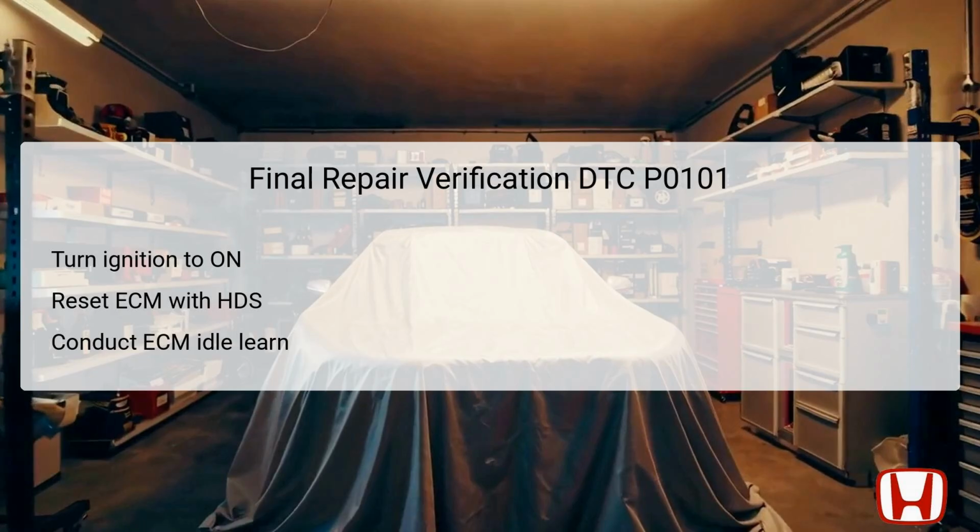Begin by turning the ignition switch to the on position and resetting the engine control module, ECM, using the HDS. This process clears any previously stored codes and allows the ECM to reset its parameters. Follow that with conducting the ECM idle learn procedure, which helps the ECM adapt to engine parameters after repairs have been made.